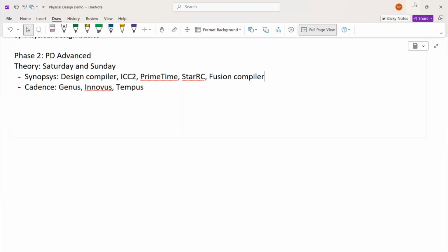Another project. See, netlist we are having. So whether you use the 14 nm file or the 28 nm file, you will be able to run the whole flow. That totally depends on which files you are having. Netlist we can use throughout in Cadence also, and this netlist is the thing which can be used commonly. Library files is what matters, like we have library files for 14 as well as 28.